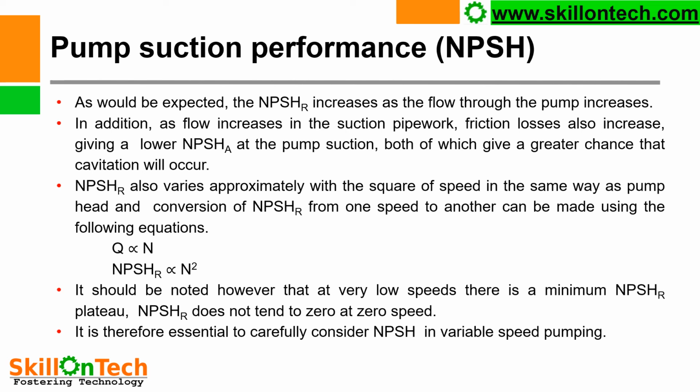It should be noted, however, that at very low speed there is a minimum NPSH required plateau. NPSH-R does not tend to zero at zero speed. It is therefore essential to carefully consider NPSH in variable speed pumping.